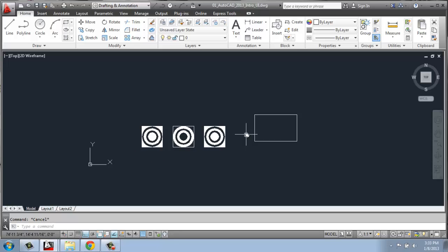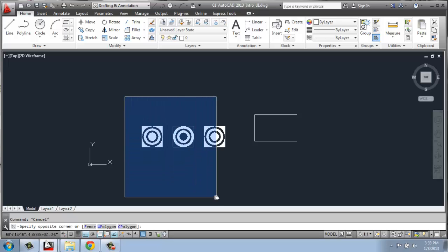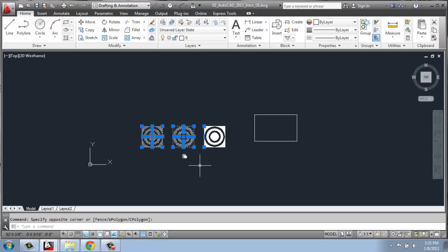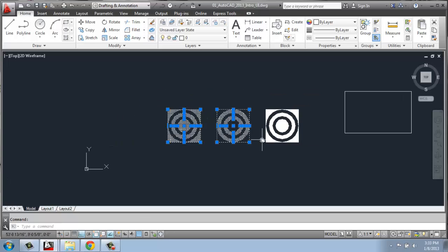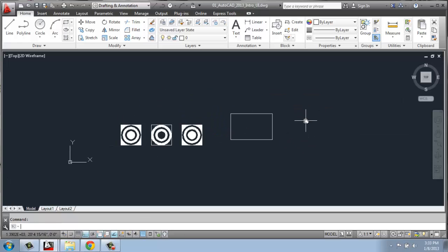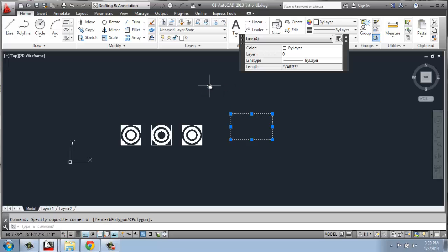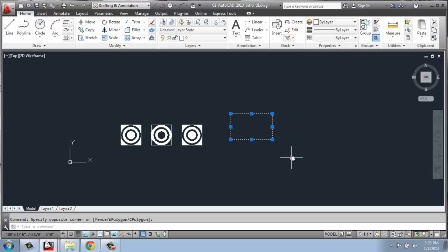And once you get into something more complicated, you'll see how it's very useful in maybe picking out smaller elements, but not everything that you didn't mean to pick, for example. So if you're working on floor plans and things like that, you can see how that would be really useful. So it's simply clicking, holding down the Shift key to deselect, and then using window and crossing selections to do basic selecting within your drawing.